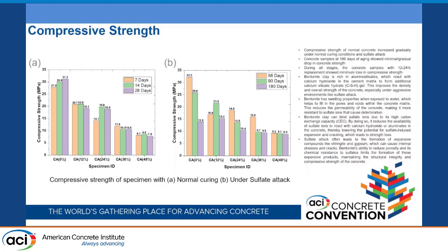natural ingredients of concrete. During this analysis, we found that there could be possible two to three reasons which are responsible for retention of concrete strength. The first reason for retention of the concrete strength, especially between 12 to 24%, is the high percentage of aluminum silicate in the bentonite clay, which can be beneficial in concrete, making more CSH gel.